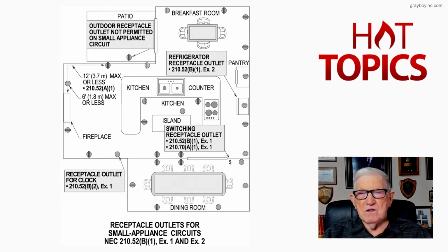And then you notice the same thing that we talked about. If you have a switched outlet, that can count as one of the required receptacles if you locate it properly by the code. And again, you go around the wall with that 6 foot measurement that we talked about from the door, then every 12 foot. And again, you need to have a receptacle within 6 foot in either direction in the center. And that's a very good rule of thumb to use if you're setting boxes when you're at the framing stage and you just have the stud there. That's a good way for you to do that.